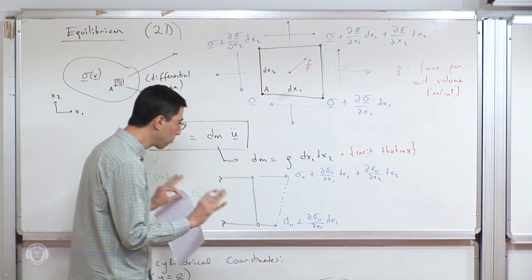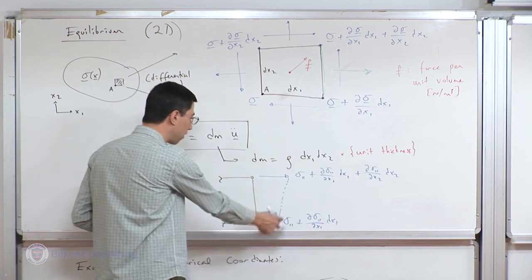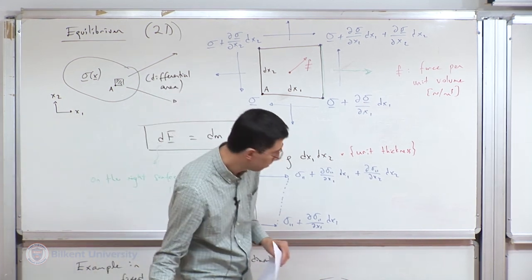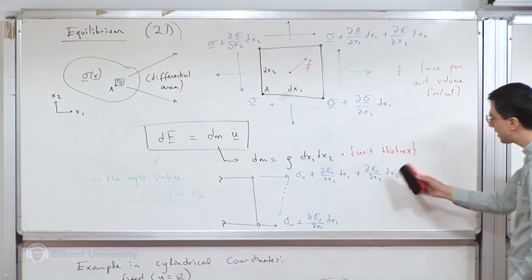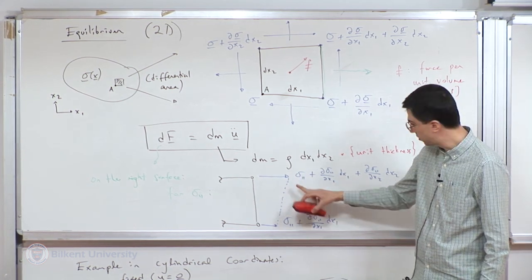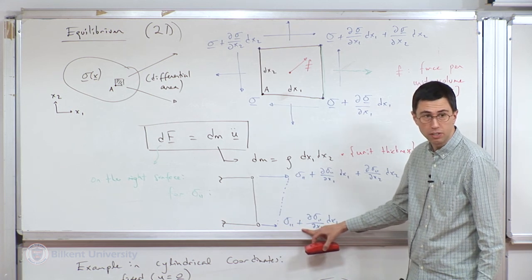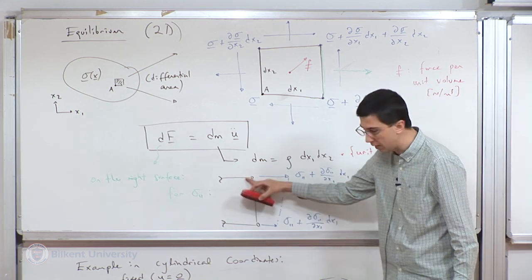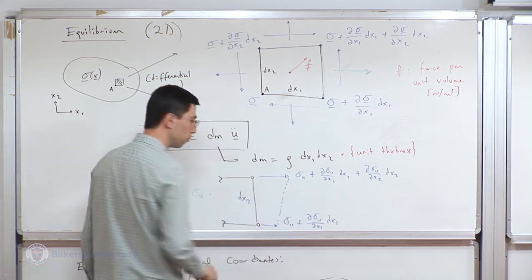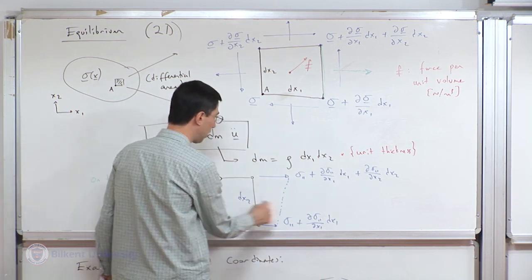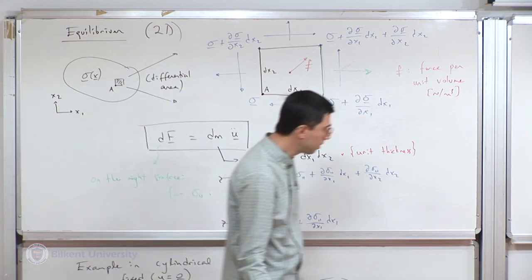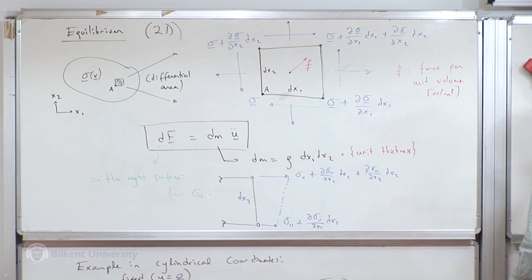Okay. So now I'm going to do the same thing without drawing, of course, every time, for all components of the stress in all directions. Again, it has unit thickness, but essentially I need to sum this component with that component, divide it by 2, and multiply it by the height, which in this case is dx2. So dx2 times that plus that over 2, times unit thickness, would be the net force in the one direction due to the sigma 1, 1 component.